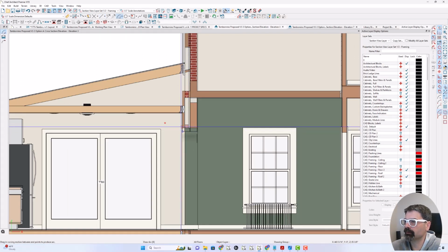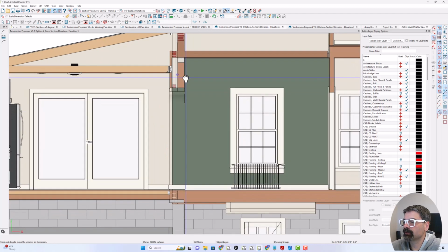I'm not sure why the program does that, but anyway, that's my screen drawing program that does that zooming in. So I move this wall over to here, and then there's this room that we can select, change the room height to 8 foot to match this one, and then move it back. Already ahead of you, already did that. It's already to here, still to here.